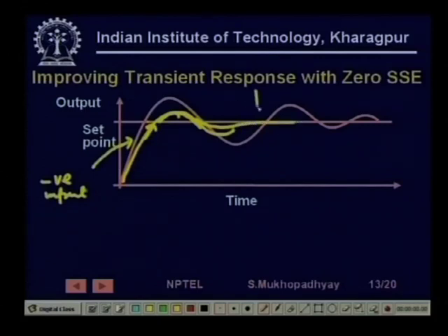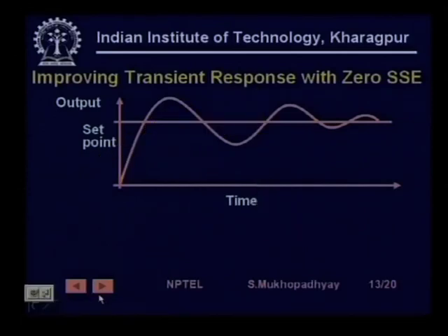So you see it will not oscillate. We want that it does not oscillate so many times, but rather follows this yellow curve, maybe does a small overshoot and then immediately settles down. This is the kind of curve that we want. Now it turns out that this kind of curve we can obtain if we add a derivative term to error.